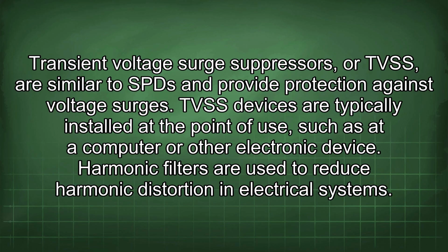Transient voltage surge suppressors, or TVSS, are similar to SPDs and provide protection against voltage surges. TVSS devices are typically installed at the point of use, such as at a computer or other electronic device.